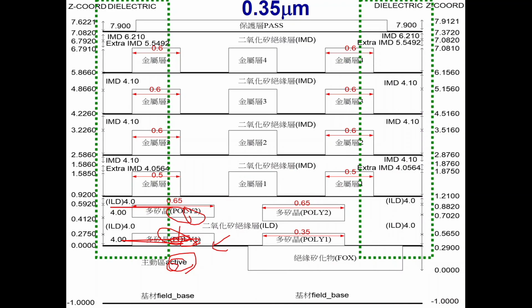Poly 1 and poly 2 are used to form that horizontal parallel plate capacitor. And above poly 2 we have metal 1, above metal 1 we have metal 2, and then metal 3, metal 4, and so on, all the way up. Above it we have the chip fully covered by glass, for protection, to insulate the whole chip from the air, because in the air we have oxygen, and the oxygen will make all those metal layers get oxidation very easily, right? Such metal oxidation is really harmful.